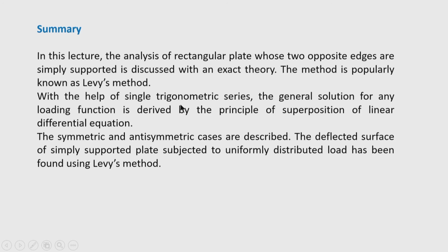So, that we have utilized, and we have compared the results for a rectangular plate simply supported along all edges, analyzed for deflection using Levy's method, with the results obtained from Navier's method, which are also available in the textbook.